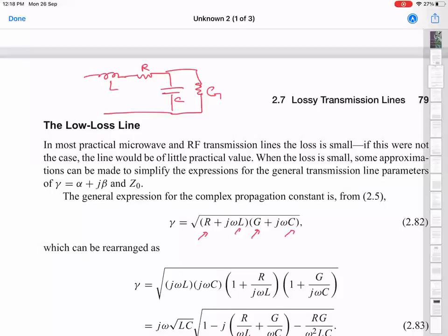In the case of cryogenic experiments, where the signals have to propagate from a room temperature environment all the way down to the cryogenic environment, there is a different need, which requires your transmission lines to be actually lossy. And that is related to the fact that the thermal noise which is present at room temperature, you don't want it propagating all the way down to low temperature.